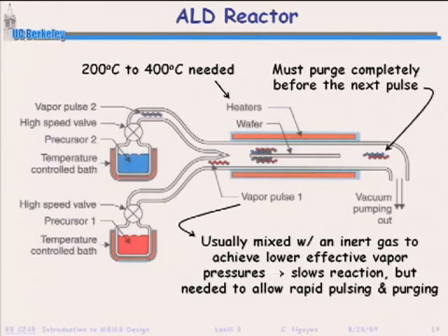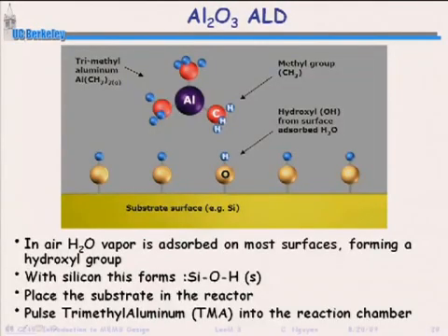Okay, so here's an example of the ALD reaction here. And so this is just at the molecular level. So usually what happens is you start out with your substrate. Maybe that's just bare silicon. For most of these reactions, you want to hydroxylate the surface. And that way you just put water vapor in there. Just water vapor from the air gets on the surface of your structure. And usually what you end up seeing is OH bonds just sticking out from the surface. And then you've got a monolayer of these things covering the whole surface.